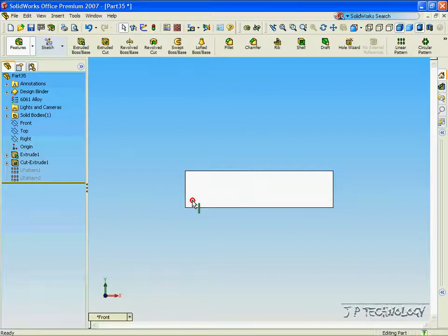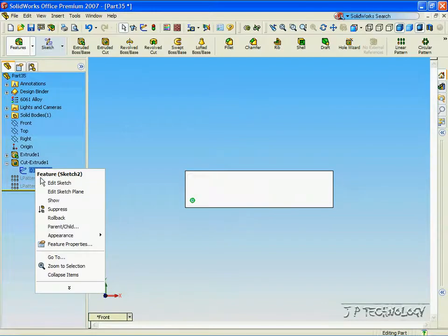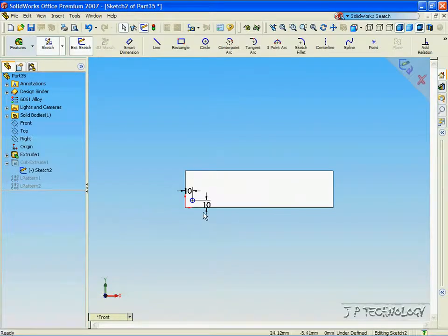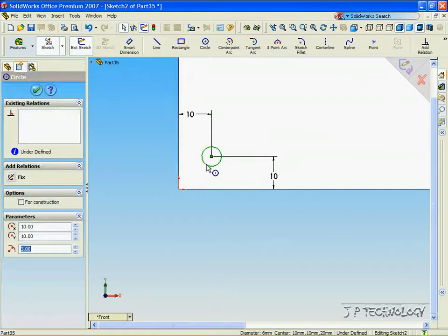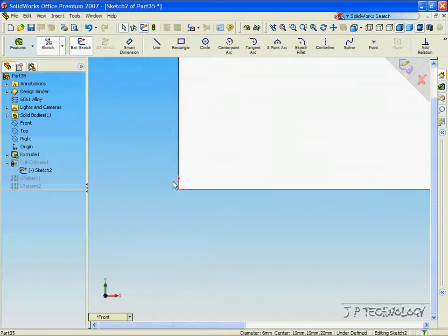Now we're also able to change the initial extruded cut, and it will also influence the linear patterns that we have both suppressed. Now, let's open up the extrude cut, right click the sketch, click edit sketch, and let's zoom in. Now let's delete this circle and let's make a square.